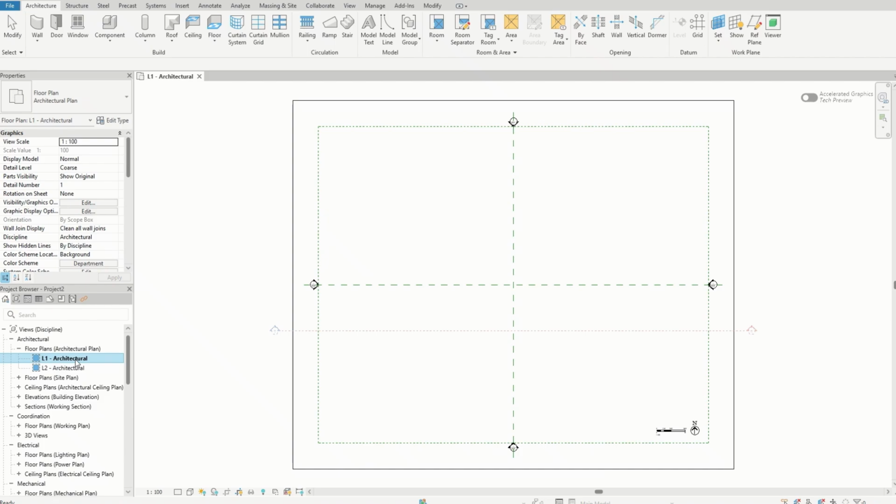Part A. Extrusion, Steps 1 to 22. Step 1 to 2. Start and open the working view. Create a new Revit project, then open floor plans to level 0. If your template names levels differently, that's okay. Just stay on the same level when I call it out, unless I tell you otherwise.